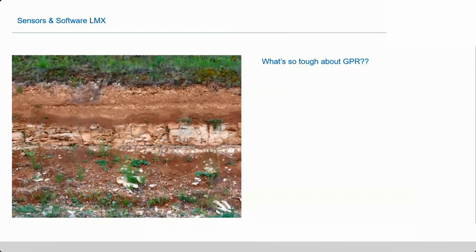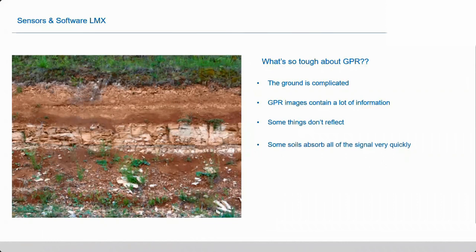So what's tough about GPR? Well, the ground's complicated. GPR images themselves contain a lot of information. Some things will not reflect. Some soils absorb all of the energy very quickly. And GPR detects everything, not just the stuff you're looking for. You must understand the context.